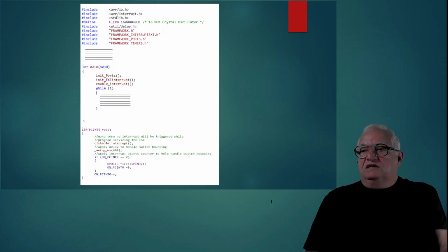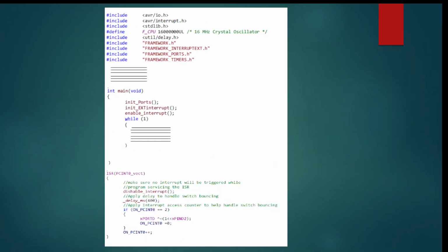Now, this is the program. This is what I wanted to conclude with, showing this program. So you would have your include up here in the tab. Next, these lines represent all your program initialization, interrupt initializations, and so forth. Next follows the main routine. You have your main routine, your while loop with all the lines of code, and then this is where the main ends.